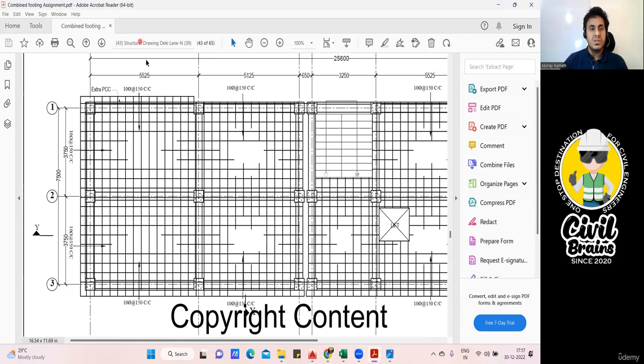If you remember, this is actually a beam. This is your beam, this is your beam, and this is your beam. This is the slab we consider. But practically, if you see here, these people have taken a small offset. You can see this offset here. So it's a small cantilever portion. Here also, and here also a small cantilever portion. So your reinforcement will go slightly outside like this. This is actually the beam ending, but your reinforcement will go here.